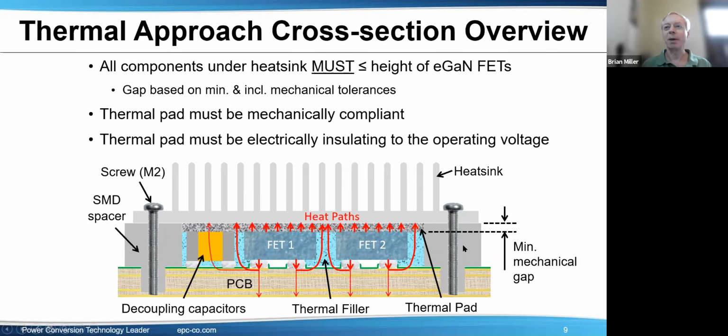And again, this shows the spacers. A little note here is that besides the capacitors, resistors also work well to conduct heat. And there are also things that look like resistors that are actually aluminum heat spreading devices that are for sale. So those can also be used to enhance the heat flow from the PCB to the heatsink if that's needed.